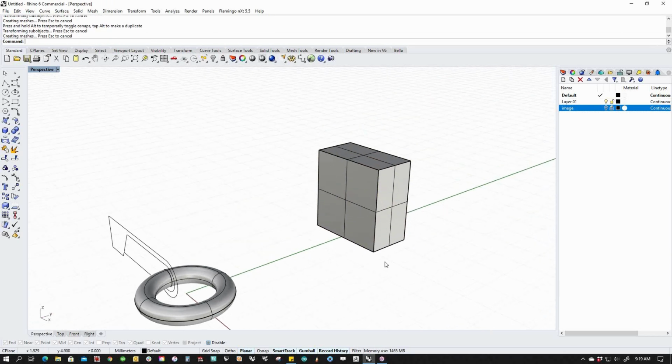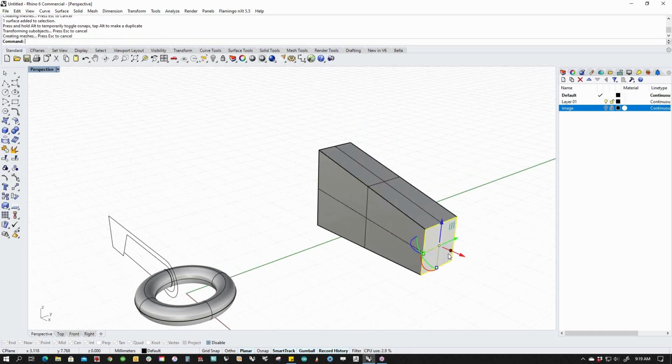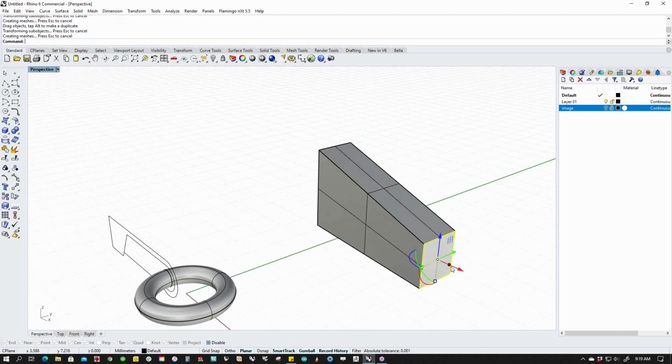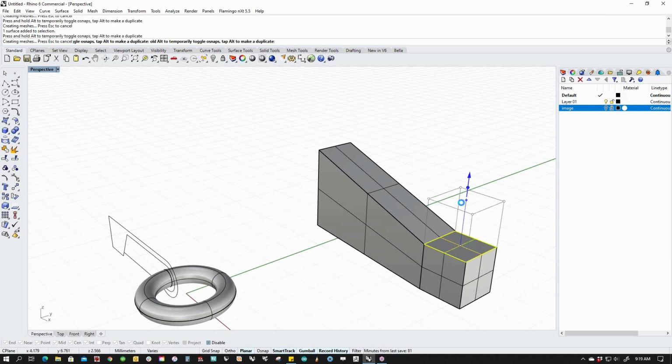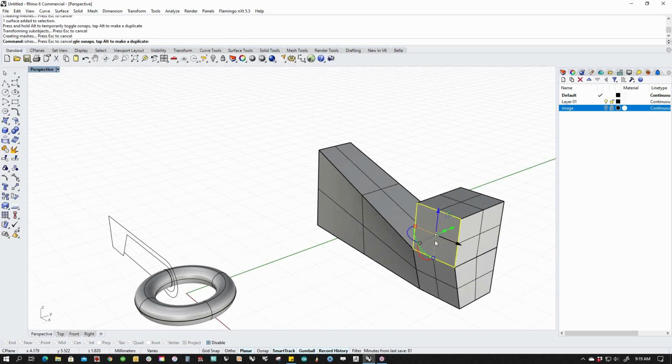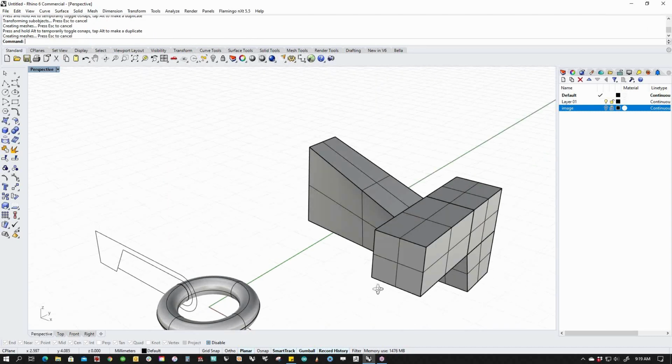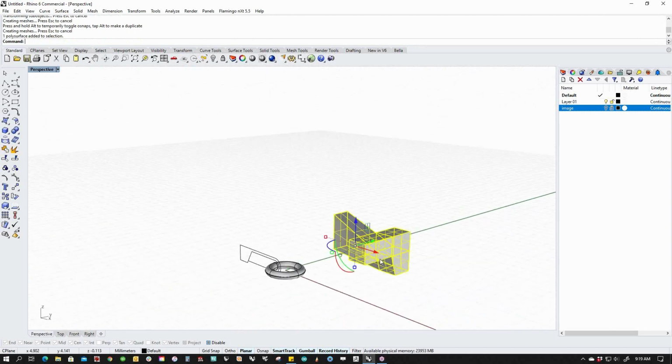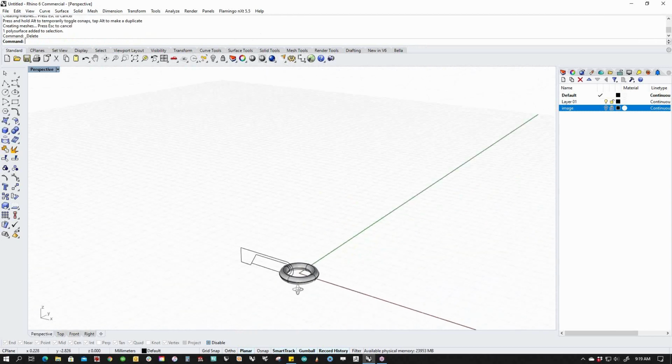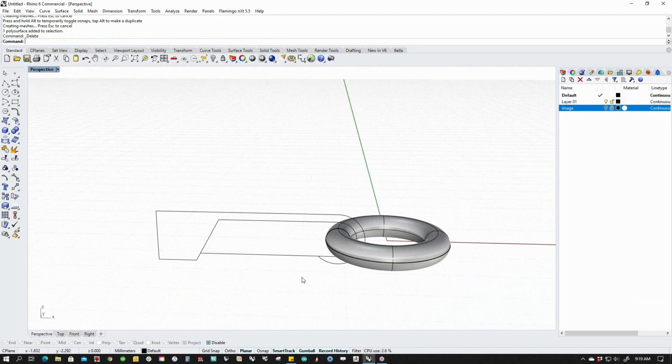Whereas if there was any degree 3 information in here and I pulled it, you would get all sorts of crazy isoparams and stuff. So when you work with basic shapes like this, you can make modifications to the basics and then go back and fill out this stuff later. And so I think that's probably what I'm going to do here.